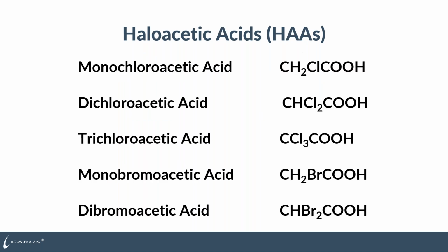In the case of haloacetic acids, referred to as HAAs, typically when you get your report back from a certified lab, you'll see HAA5 listed. And these are the 5 that they test for. So monochloroacetic acid, dibromoacetic acid. So you can see the list there. Typically there's a spread, but mostly you're going to be toward the chloroacetics. So the mono, the di, and tri, that'll typically be your largest.